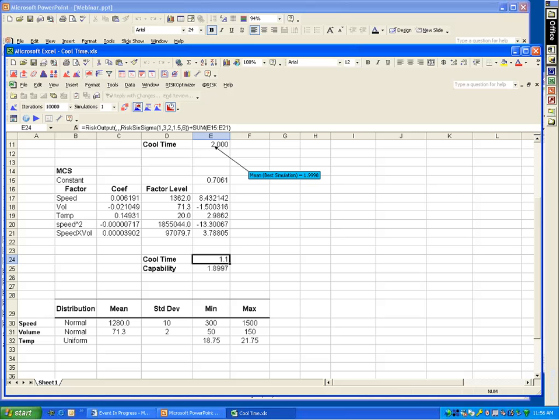So this metric combines essentially measuring the distance of the mean of the response from the spec limits, as well as the variation in the response, the tails anyway, from the spec limit. So it's getting at how much of that distribution of the response is beyond the upper and lower spec limits.